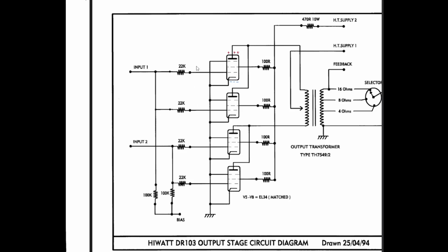I would say equally, but that's in an ideal world. Really, it's based on the demand of each tube and what their individual gain values are within the range of the tube set. Okay, so let's take a closer look now at the actual bias circuit.